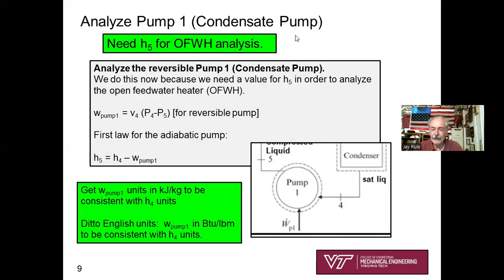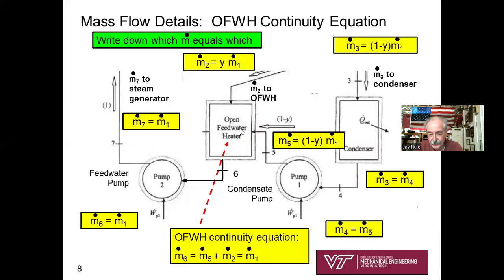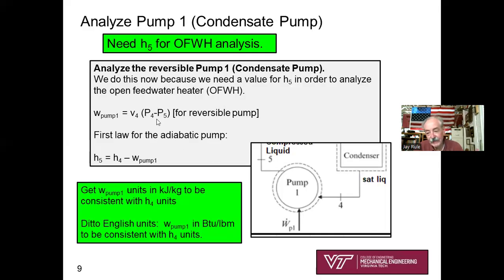Now, when you say, okay, I'm going to have to perform a first law analysis on the open feedwater heater, so I've got to plan my work. If you think about the open feedwater heater, well, here it is. You see that you need h5. Let me go backwards. If you're going to analyze the open feedwater heater, you need h5. That means that you've got to study pump 1 before you study the open feedwater heater. So how are you going to get that? Well, pump 1, let's see.